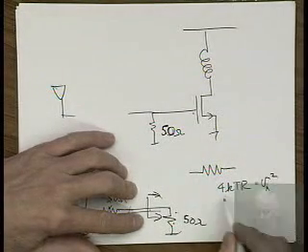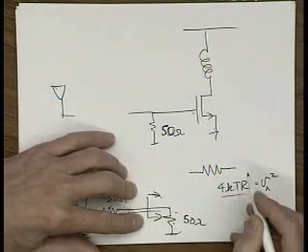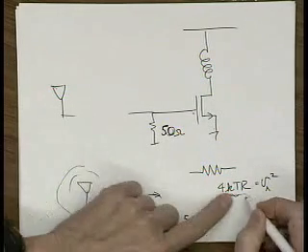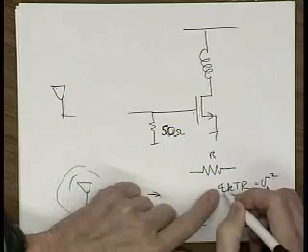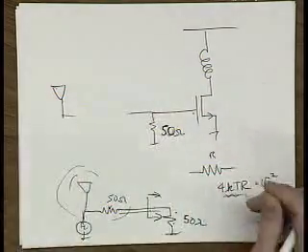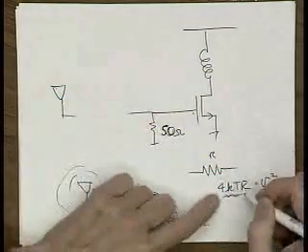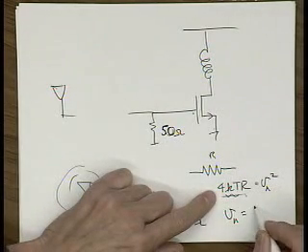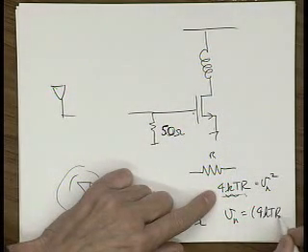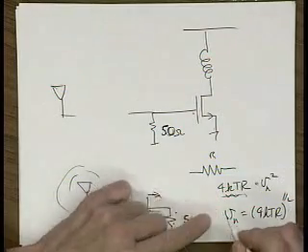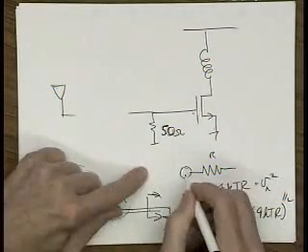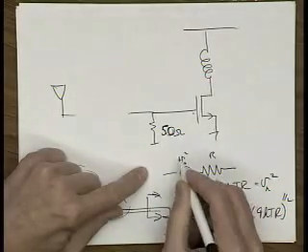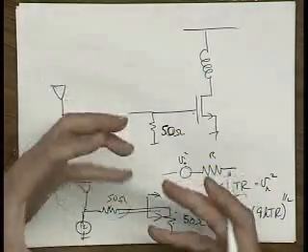The noise power is 4kTR. kT is the thermal voltage, R is the value of the resistor, and the 4 comes from equipartition arguments. So the noise voltage is equal to (4kTR) to the 1/2. You model it as a little noise source, and we usually think of noise power because it's a random fluctuation.